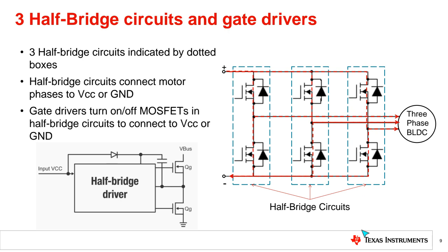Also, we have the half-bridge driver. This is the gate driving approach. Why are we using one half-bridge driver? Because in the brushless DC motor, we generate complementary signals. One PWM will be on, the complementary of the other one will be zero. You cannot generate PWM for two of them at the same time. It's called shoot through.